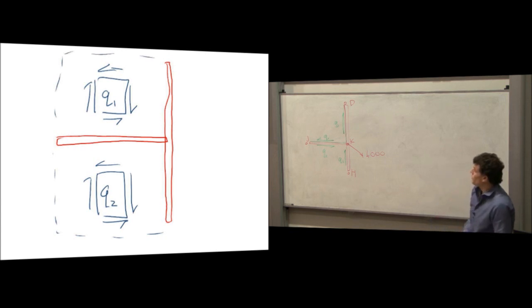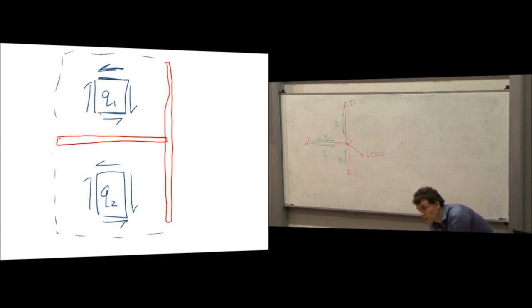Now, when we read this diagram, this tells us if we cut somewhere, then the shear flow acting above the cut will be to the left, or the shear flow acting on the outside of the bottom of the cut will be to the right. What we're actually doing is cutting out most of the panel, but leaving the slightest little bit left over. So there's an infinitesimally small little bit of panel left there.